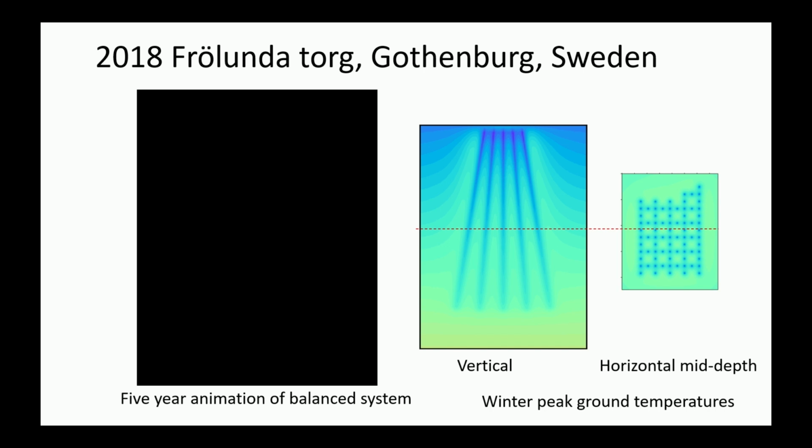And if you have a balanced system, there is a certain reach of the wave, the heat wave that goes out from the borehole and back again. So going beyond this reach doesn't really change much when it comes to thermal influence. So there's a difference if you have a heat extraction or heat rejection system only, because then it will spread across the whole system.